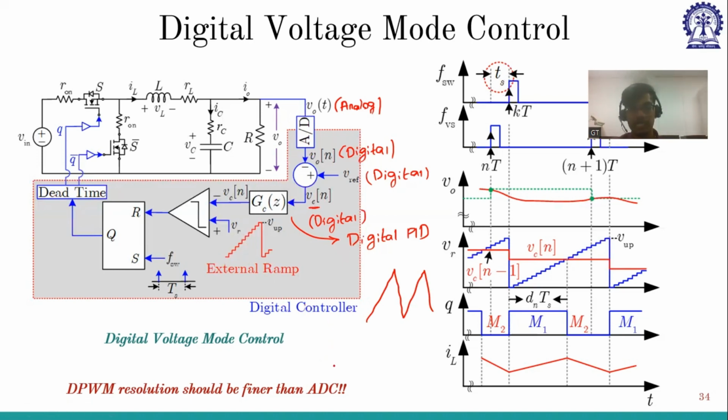So in digital, it has discrete values, say 0, 1, 2, and so on up to the final value, and then 0. Here in analog we have infinite resolution. It is smooth. Whereas here, it is not smooth. It has some minimum step size, which is the counter. This minimum step size comes in the case of the digital ramp, which is not available in analog.